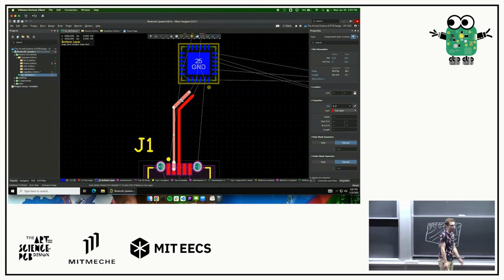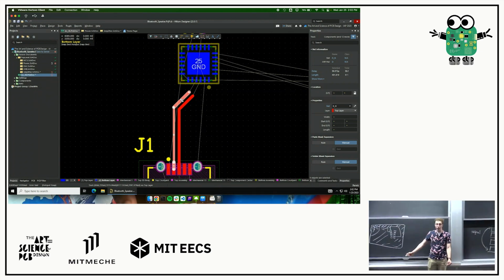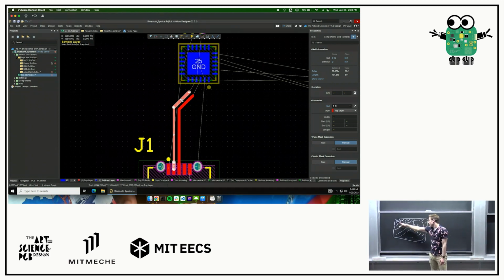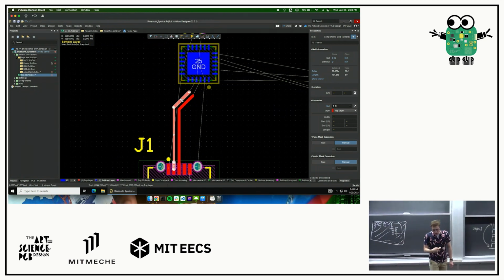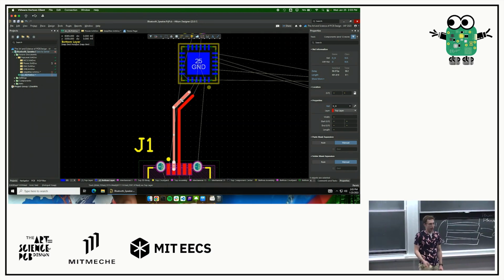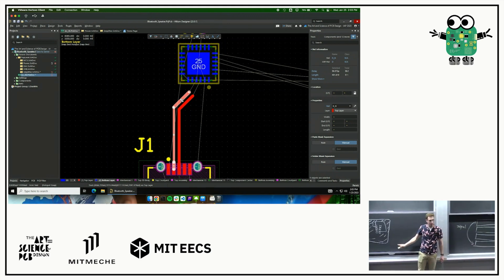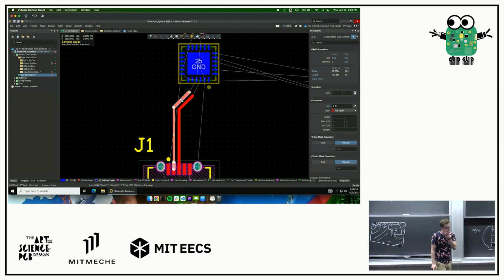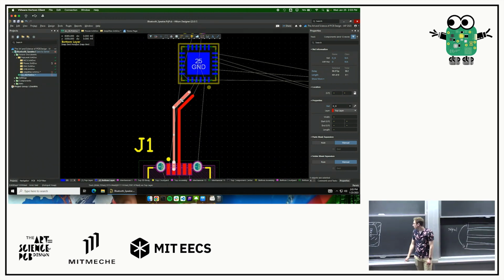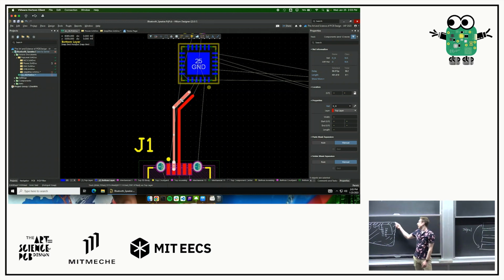In the reference design that we gave you, we put a ground pour on the bottom layer. So on the top, it's nice and sparse. You just see a bunch of stuff like this. And then on the bottom, we have only a handful of traces, but a massive ground pour. Depending on your exact situation, generally it's preferred to have a ground pour on the bottom and top layers of our boards. For the reference ones that we gave you, for a couple of reasons, we decided to only do it on the bottom layer. But when y'all route yours, you're welcome to put a ground pour on the top and a ground pour on the bottom if you so desire.